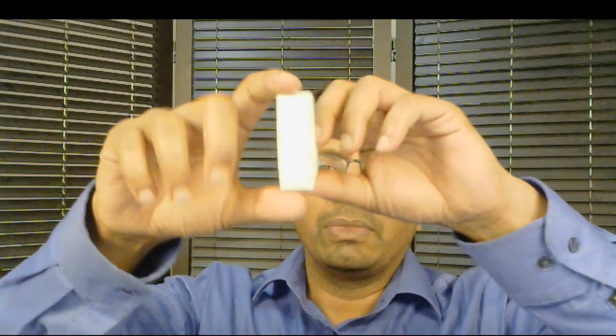Typically you would pick the front view because it has the most information, and then give either the left or the right side view, and then the top view. That will give you all of the information that you would need to construct the object. Just as an exercise, we created the different views and saw how the object actually looks. Then we asked, what happens if I'm given only the front, and there's a piece that's bitten off from the back? So I have those two views. Then we looked at how we can construct the missing top view using the information that's only available in the front and the right side view.